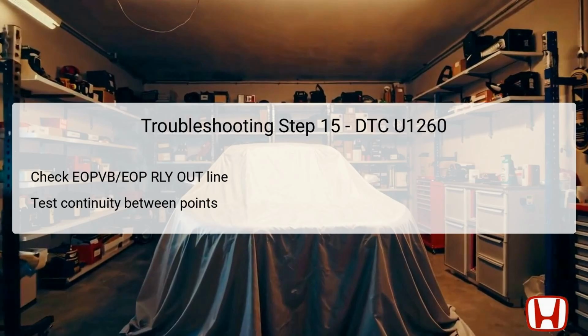This step is crucial in confirming that the auxiliary transmission fluid pump can indeed receive signals from the relay, ultimately allowing for the proper functionality of the transmission fluid management system. Any interruption along this line may lead to the reappearance of the U1260 DTC and associated transmission issues.